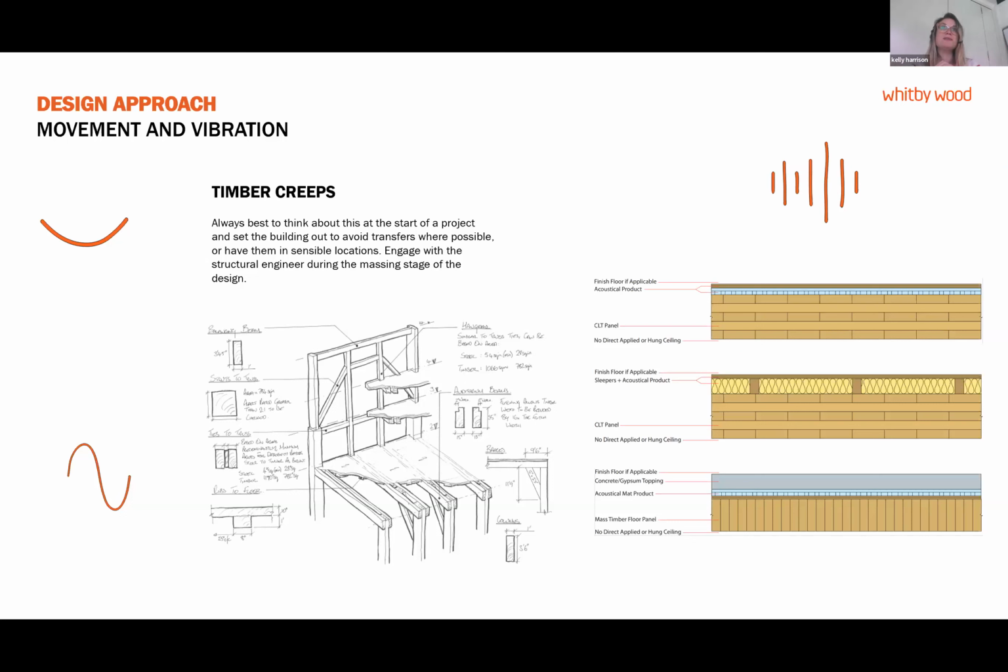And especially when you're looking at parts of the building that support things that are brittle, or facades or glass, we have to limit deflections. We have to start thinking, maybe you're thinking more about deflection in stage 2 than you normally would with other materials. So that's one thing to think about.